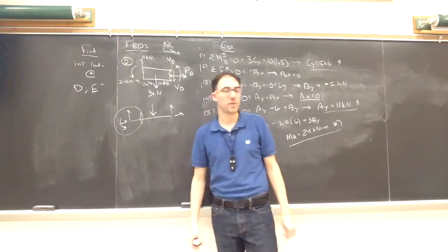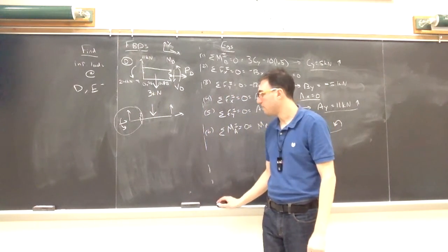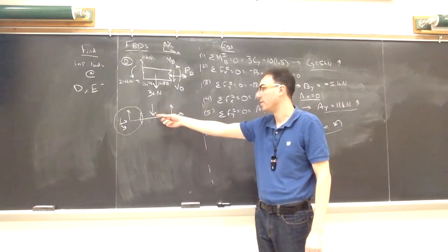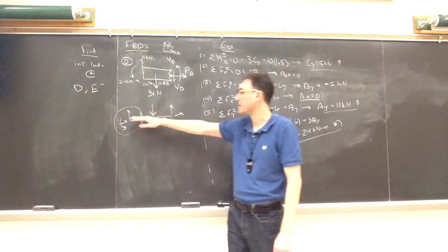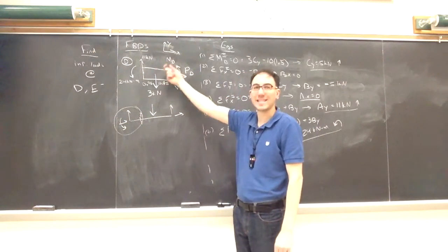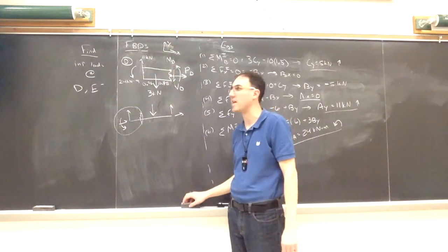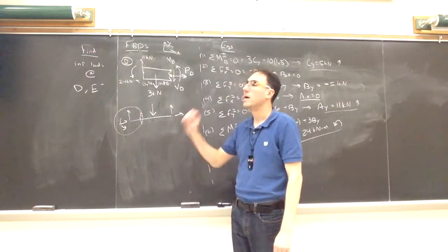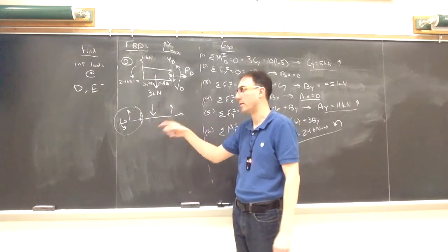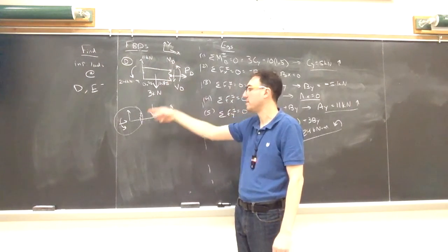And that's the difference we see externally. Turning that distributed load into a point load is fine. It doesn't affect the reactions at A or at B. But internally, that simplification does matter. There is a difference whether this did have a distributed load or whether it actually had a point load. Internally, it makes a difference.